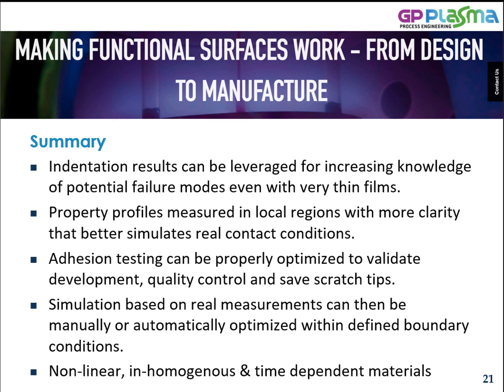So in summary, indentation results can be leveraged for increasing knowledge of potential failure modes, even with very thin films. Property profiles are measured in local regions with more clarity that better simulates real contact conditions. So in summary, we leverage indentation for stress and other interesting property profiles to inform better materials and process design at a rapid development pace. Indentation and scratch data can be leveraged as design inputs. The simulation is based on the real measured response of your system in question. The optimization process uses the measured information to forward predict when the system will fail based on a change of conditions.